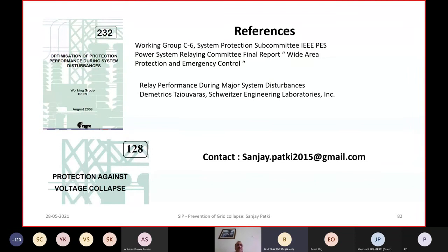Yes, basically, sympathetic inrush causes a voltage dip depending on how strong the source is while charging. So that momentary voltage dip and recovery due to the inrush phenomena on one transformer can cause a sympathetic inrush on the transformer which is already in service. Usually this will not be as high in terms of magnitude, but second harmonic content will be high even in that. So this sympathetic inrush phenomenon is prominent if the source is stronger behind the transformer.